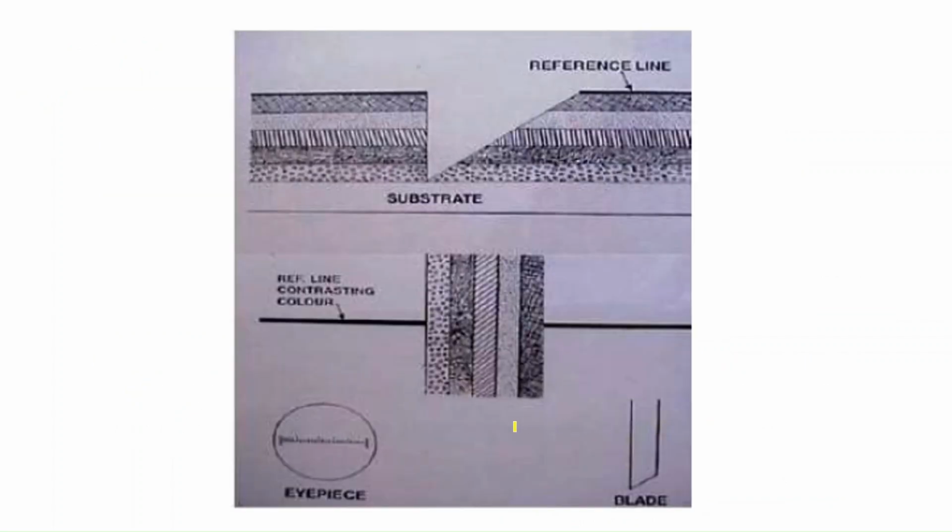Here in this photograph you can understand, this is your coating, and this one is your substrate on which the coating has been done. If you clearly see, how many layers of coating are there? This is the first layer, then second, third, fourth, and then fifth layer. 5 layers of coating are there. Now, you can see the blade here. With the help of this blade, the cut will be done on the paint. Here this cut has been done, and through the graticule scale on the lens you will be able to determine the depth. So this is how it is done.